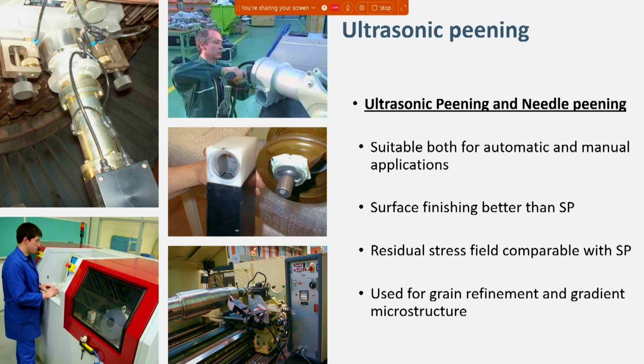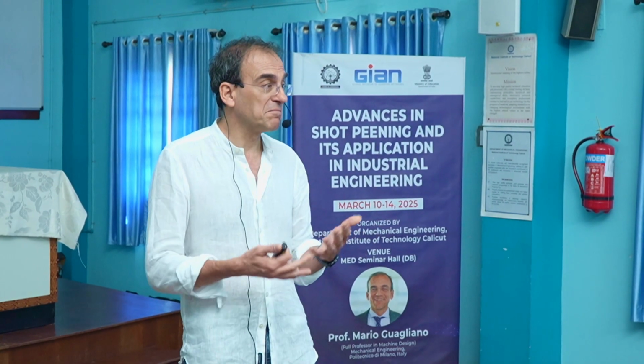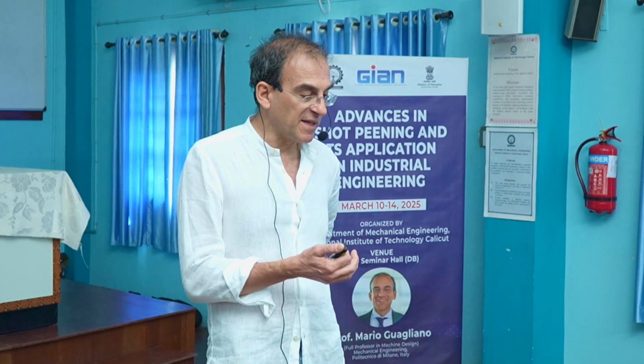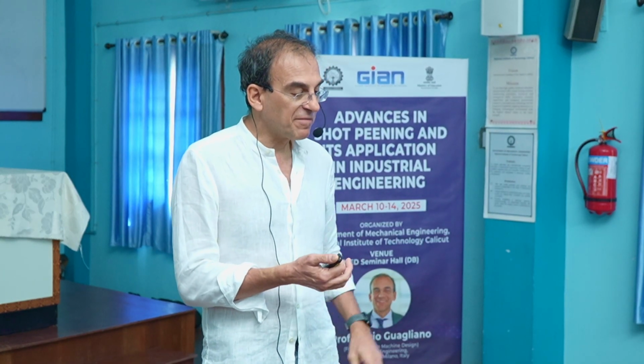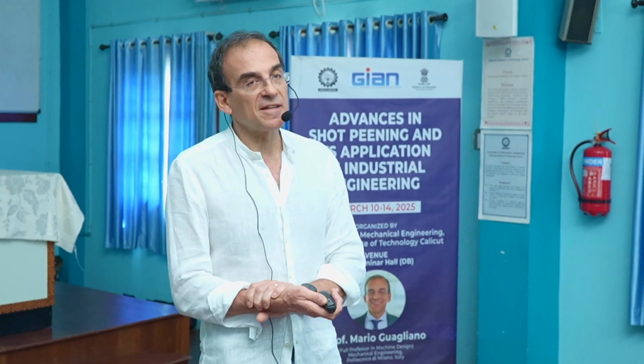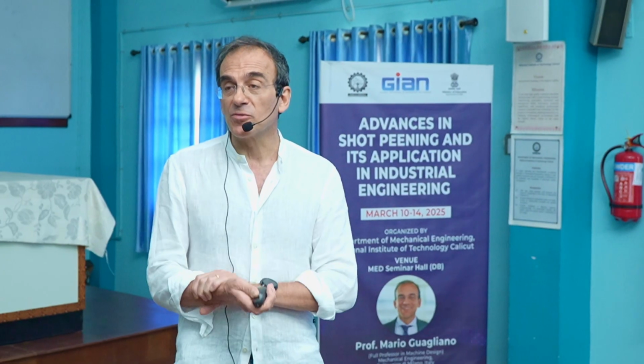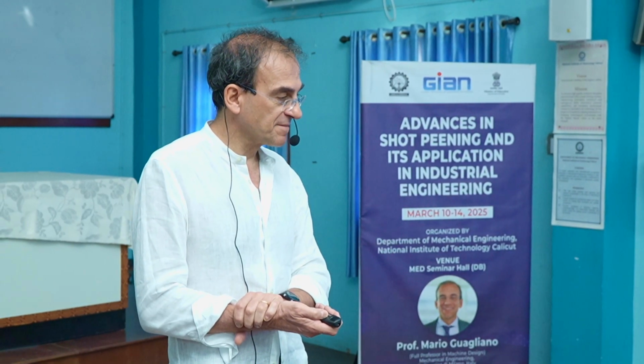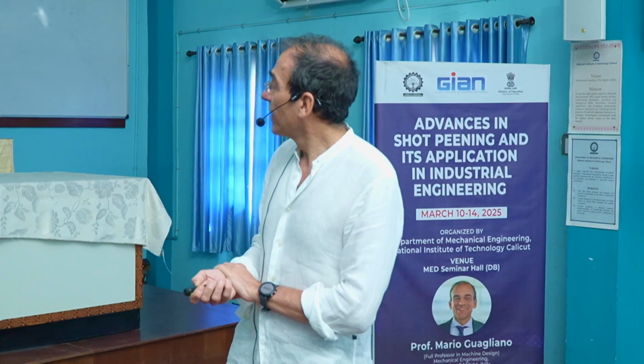The surface finishing, we said, is better than traditional shot peening. Residual stress field is comparable. No, it's not the same, it's comparable with shot peening. And grain refinement is easier than shot peening due, as we said, to the random multidirectional impacts. Any question?